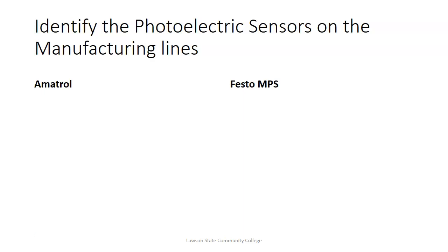It's got those light emitting diodes on the inputs. So if the input's true, the light comes on the PLC. So you can actually trigger these sensors with whatever they see, and you're checking the wiring all the way to the PLC. So if you trigger the sensor and the light comes on the PLC for that input, then you know all the wiring. Not only is the sensor good, but all the wiring between the PLC and the sensor is good, which is pretty neat.